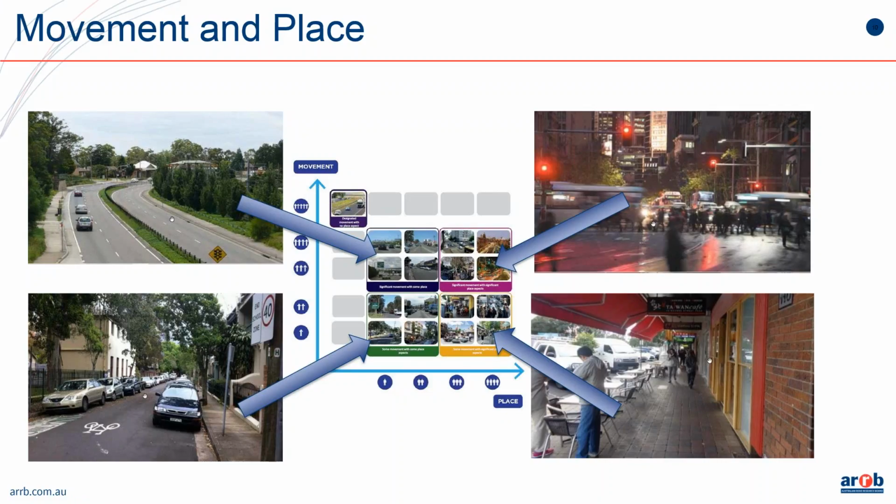There is, of course, possibility where you introduce, for example, certain priorities on ramps. So, for example, there could be a heavy vehicle priority access to ramps, or a public transport priority access to the ramp signals. So it could determine whether certain ramps will have to be provided with queue jump lanes, or more dedicated use of the shoulders for taxis and buses, and so on. These kinds of considerations, in some sense, would be related to network operation planning.